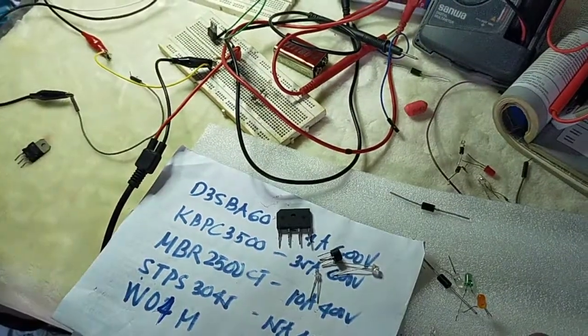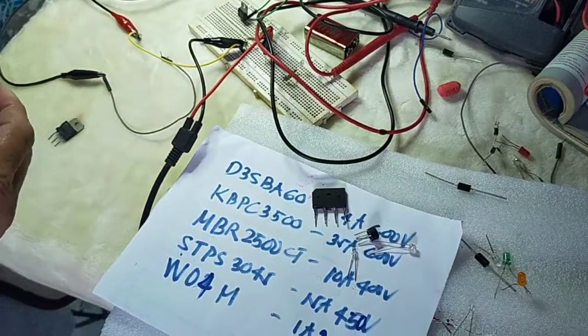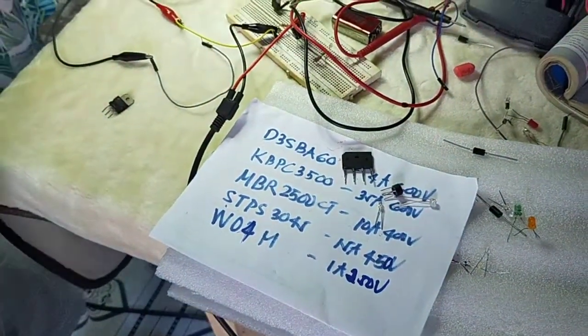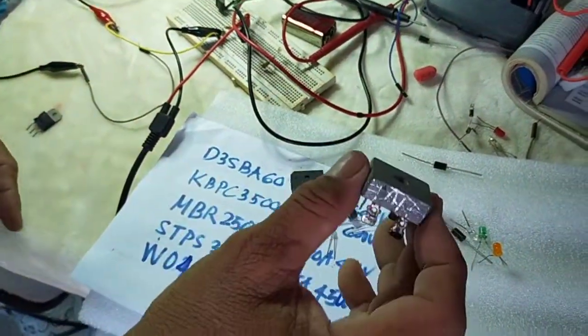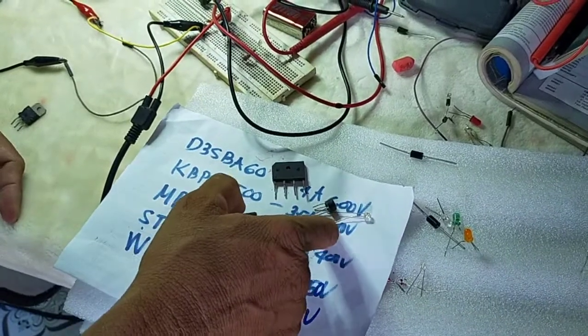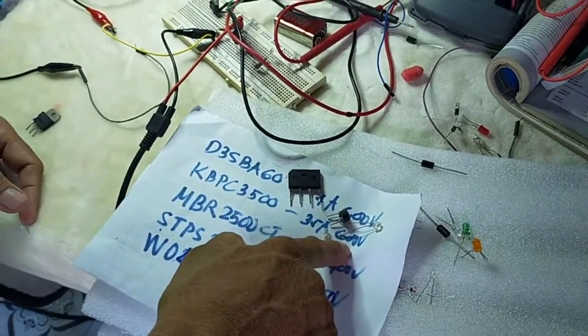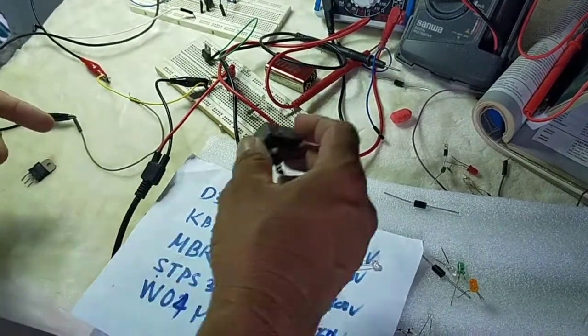This is actually applicable when you are converting AC voltage at the AC power line into a lower amount of voltage, because it is a power line. And usually the voltage there is almost 300 volts peak value for the AC power line. So this is very applicable because the peak inverse voltage is much higher. It is 600 volts. And the current rating is very big, 35 amperes.